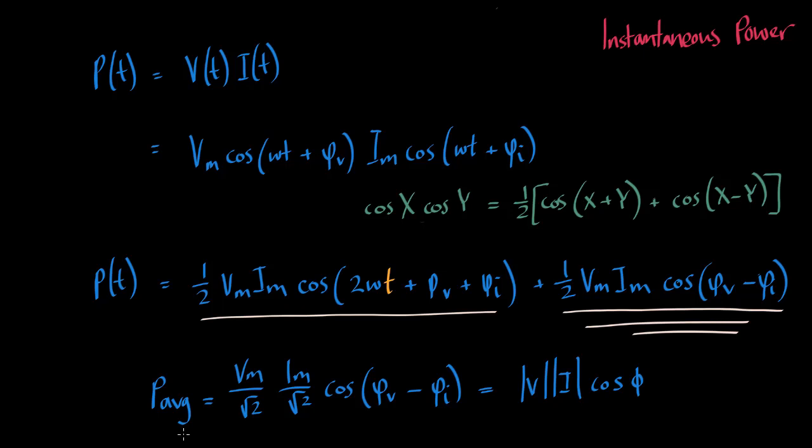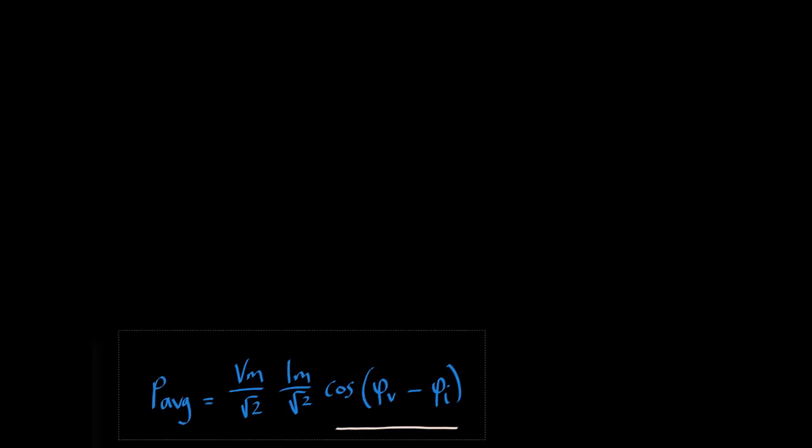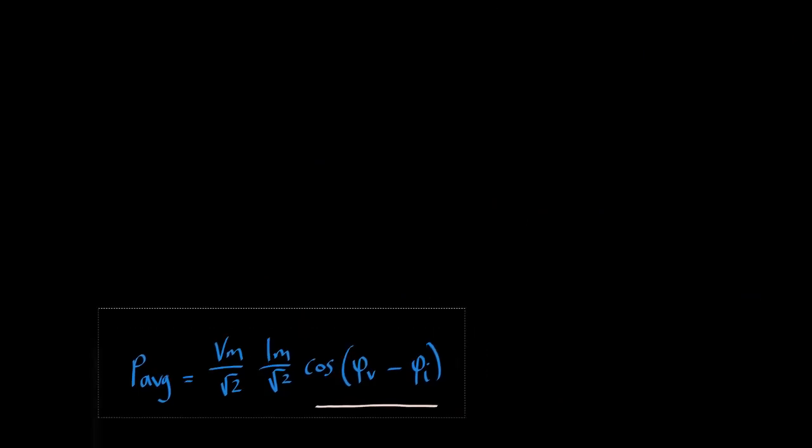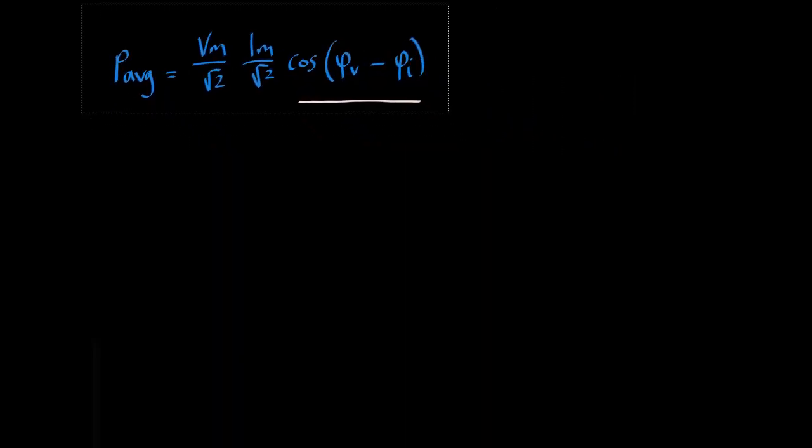Note that the first two terms are the RMS voltage and RMS current. They're followed by a term denoting the phase shift between the voltage and the current. This phase shift we've just formalized is very useful in understanding the impact of circuit components. That's because the phase shift between voltage and current in a given network is the same as the angle of the total impedance. It is otherwise known as the power factor.